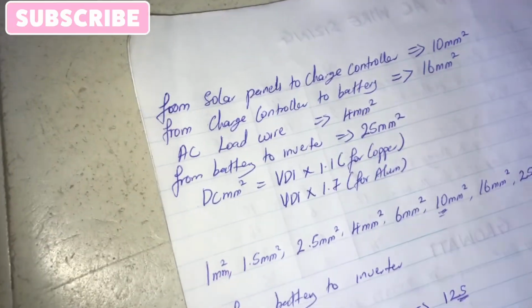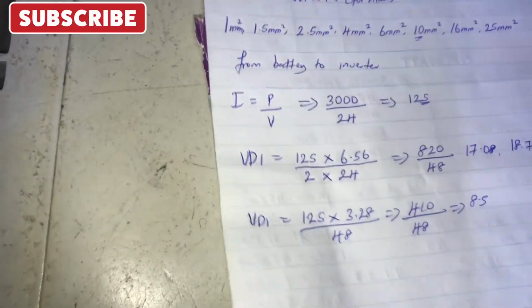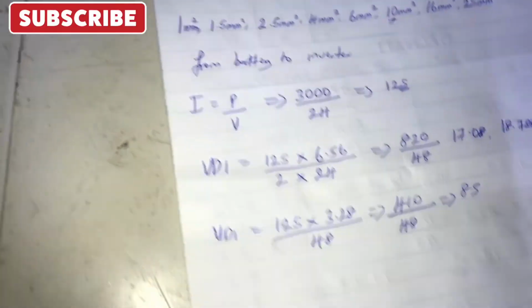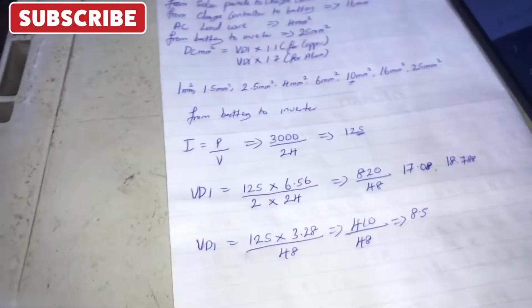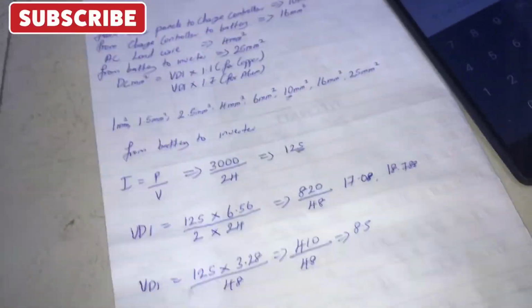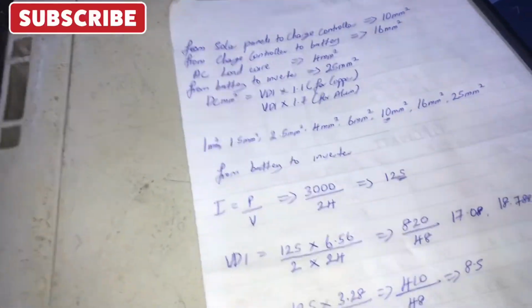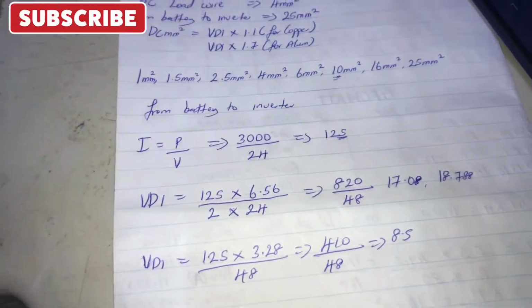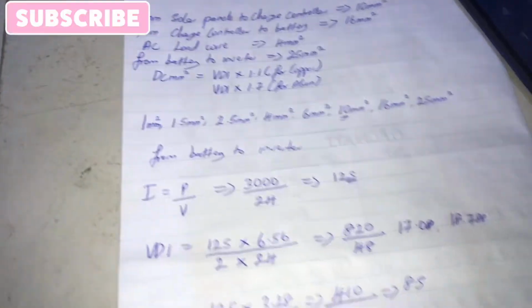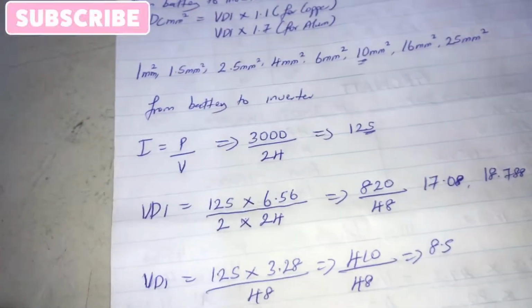So it all depends on the distance. If you are going a smaller distance, you use 10 mm. If you are going a longer distance, the wire gauge is going to increase because of the voltage drop. So you just have to make your distance as short as possible, so that you will minimize your cost, minimize your energy, and minimize your time.